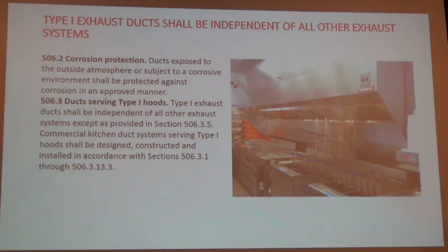Sensors and everything like that. There has to be sensors in both the ducts, I think. Right, and if it's all on one side, it becomes a one fire zone. If you got a hood on one side, a wall behind it, and another hood on the other side of that wall, that's a two-fire zone.